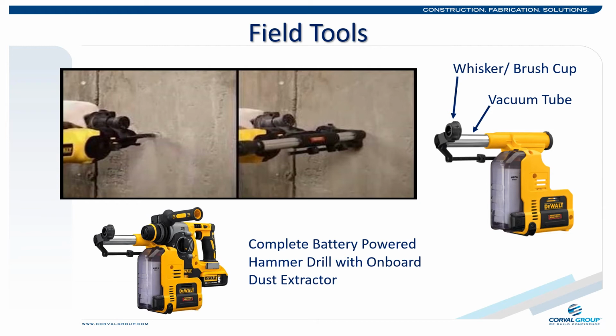It will collect the respirable dusts, but will allow the larger portions of debris to fall away. The larger debris will not generate a respirable hazard, but should be moved out of the way while the dust is being collected, if it can be done safely. In various scenarios, this is the best option when a wet method will not work. Remember that if you do go to a wet method, the importance of a GFCI in the electrical source line.